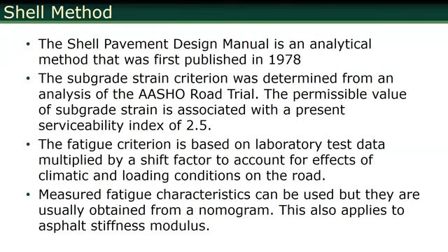Now, the Shell design method was first published in 1978. So in here, subgrade strain criterion was determined from an analysis of the AASHO road test. So there is a strain condition that needs to be limited to a certain level. Fatigue criteria is based on a lab test and multiplied by a shift factor to account for effects of climatic and loading conditions on the road. And measured fatigue characteristics can be used, but they are used to obtain a nomogram.